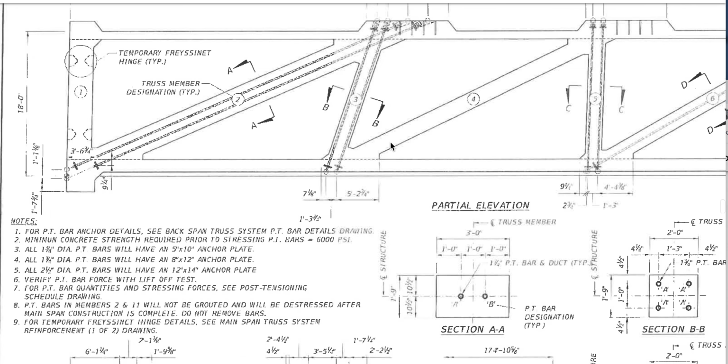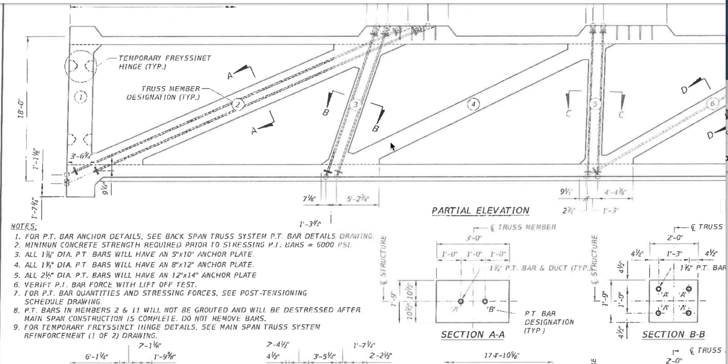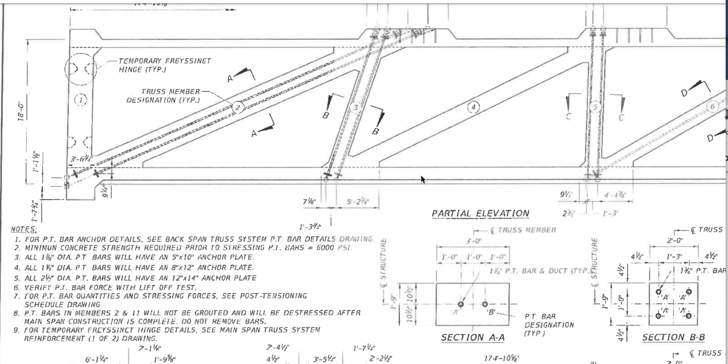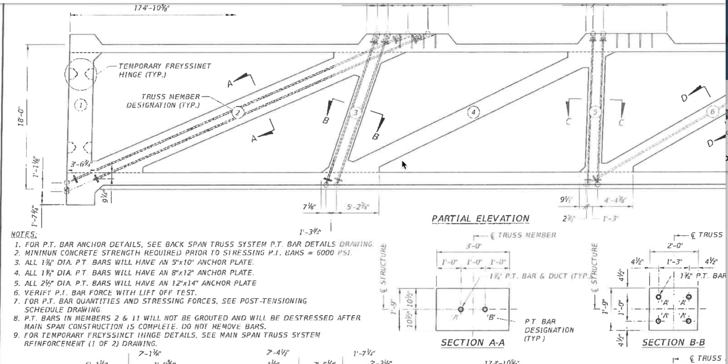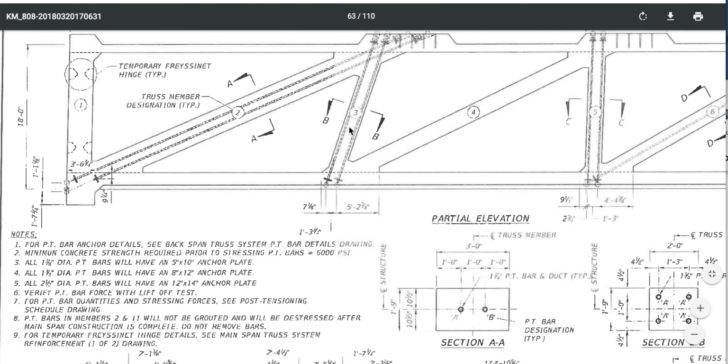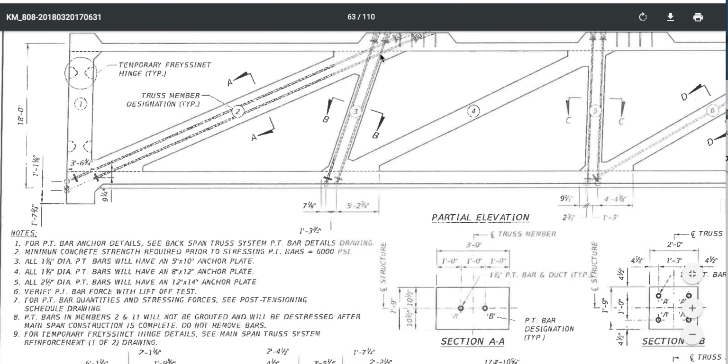Now I know in engineering everybody says it's not a matter of if your structure is going to crack, but when. I think that's terrible. Concrete is a great product as far as telling you where your stresses are, because they'll identify themselves as cracks. Steel is not going to be that easy to identify itself. It wants to hide the forces internally in the steel until you finally get something to show, like a buckling, a torsion, a shearing action.